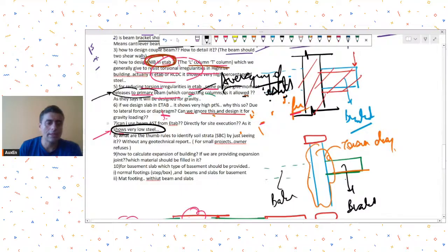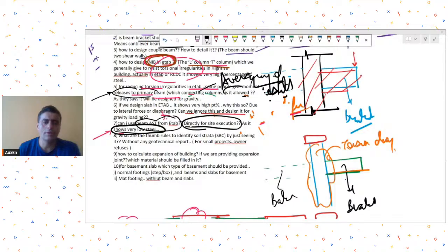So again, in my experience, ETABS may have some bugs for beam design, but generally the beam Ast is agreeable with manual calculations. So if you want to use it directly for your construction drawings, first be confident and aware of what ETABS or STAAD or any other software is doing. Once you develop that confidence, then start using it for your actual construction drawings.